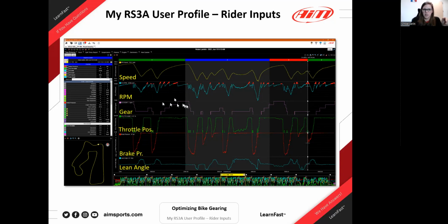Now you can actually set it up in the channel settings, and you can have a maximum threshold and a minimum threshold. I think this is really good because it gives you a very quick look at how much we're over revving. For the sake of this webinar, I actually lowered the threshold for the redline on this one. It's 500 RPM lower than it actually is, but I just wanted to show what we can do with it. Perfect, let's go to the next slide, and we'll get back to some of these things when we're in the live data.